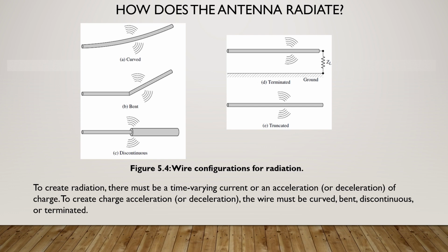When the wire is initially energized, the charges in the wire are set in motion by electric lines of force created by the source. When the charges are accelerated at the source end of the wire and decelerated during reflection from its end, it is suggested that the radiated fields are produced at the end and along the remaining part of the wire. Stronger radiation with a broader frequency spectrum occurs if the pulses are of shorter or more compact duration, while continuous time harmonic oscillating charges ideally produce a single frequency determined by the frequency of oscillation.